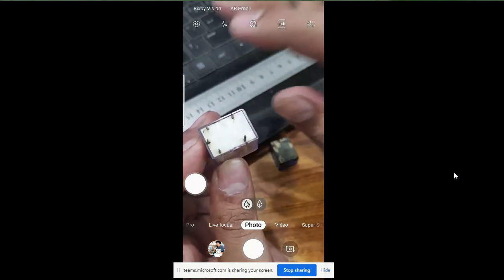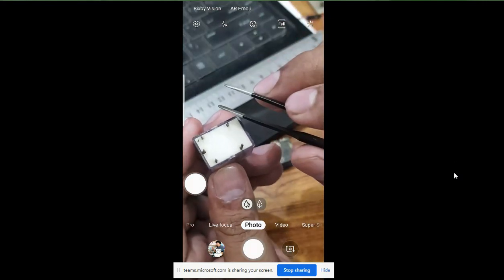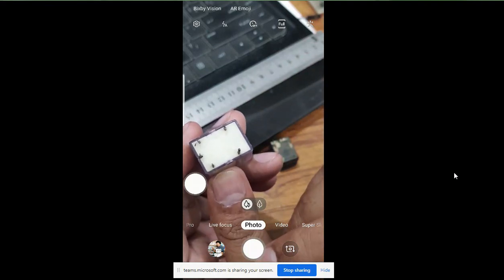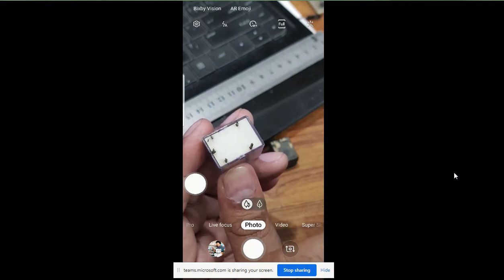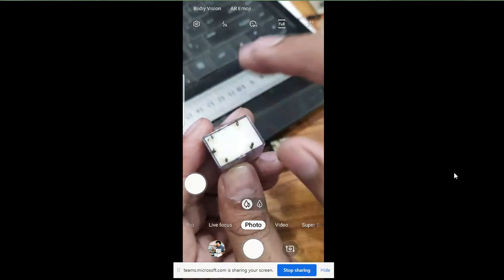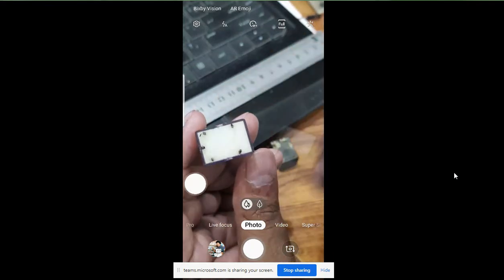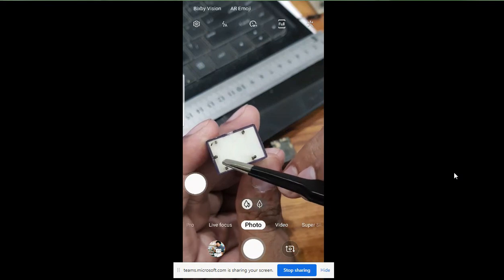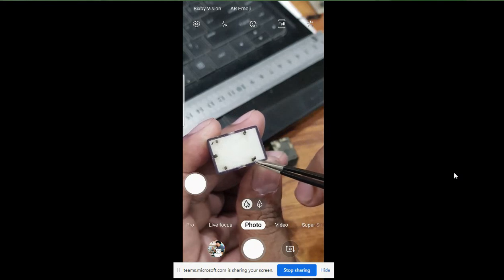A relay is an actuating device by which you can turn on anything remotely or by some other electronic process. Maybe from a laptop you want to give a signal to a bulb or a fan or something. So this relay can work in that sense, which means when you give 12 volts at this pin and this pin, you are going to have this contact, which is the common point of your relay, connected with this point, which is normally open.